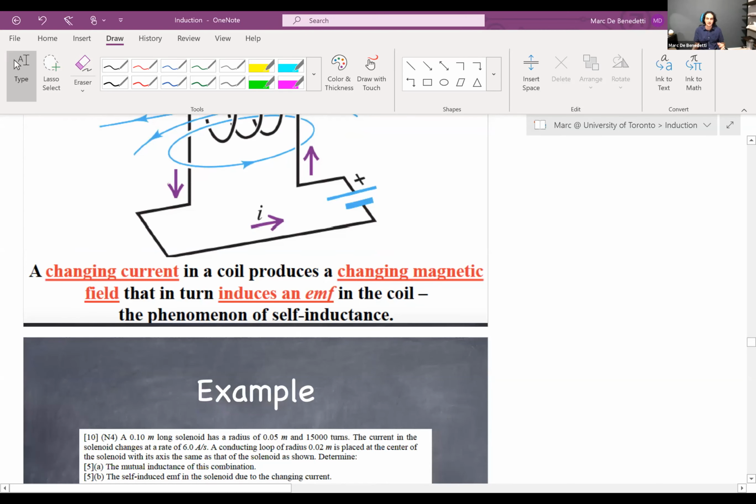The concept is that Faraday's law is Faraday's law. Any coil in any capacity that has a changing flux is going to experience a back EMF. So you can take advantage of that back EMF and induce a current in a secondary coil that is not electrically connected to anything. A lot of what we have in day-to-day lives uses this, but it also comes at a price. There's a back EMF in the primary coil that you have to battle with as well.